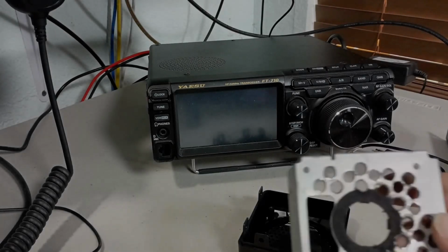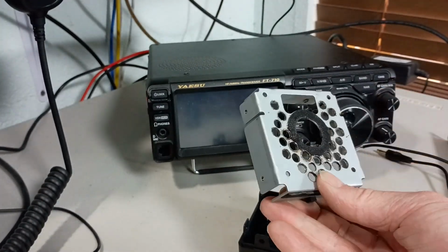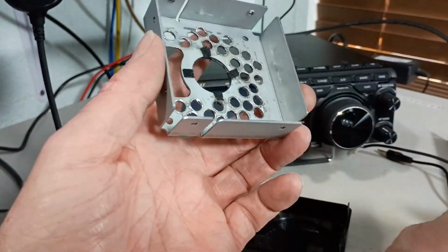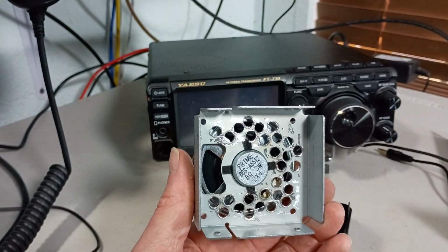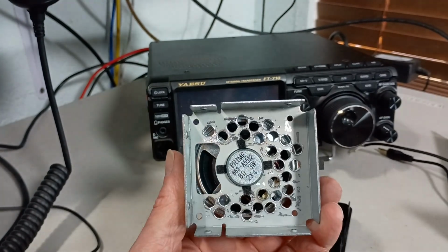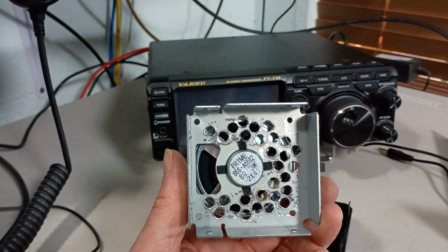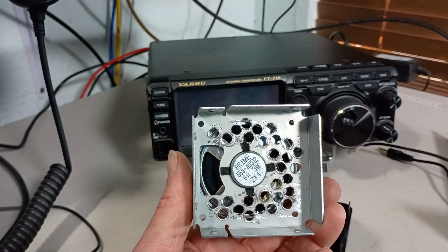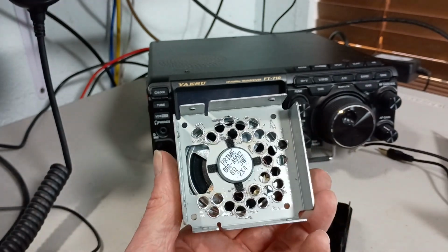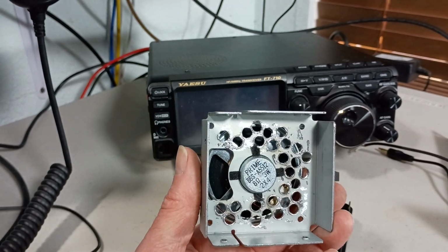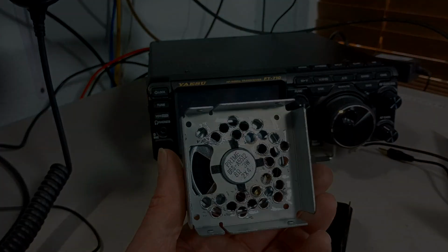Okay, back in from the garage, and what I've done, I've just punched this thing full of holes. And the idea here is that the air coming off the backside of that speaker cone should be able to easily make its way into the box. And also, with less metal up there behind the cone of the speaker, there should be less reflections off of that big square piece of metal. So I'm going to solder it back in and bolt it back together, stuff it, and we'll do another sound test. And we are back together.